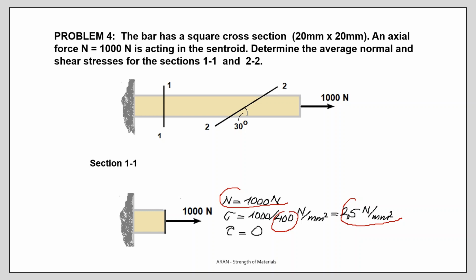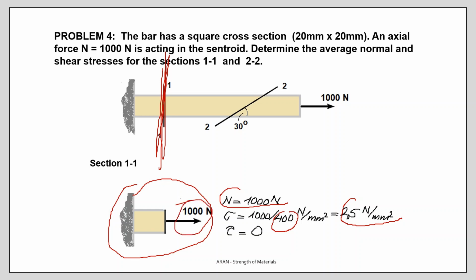Is there any shear stress in section 1,1? No, because if you take the free body diagram, there is only a force normal to the section and my shear stress is 0.